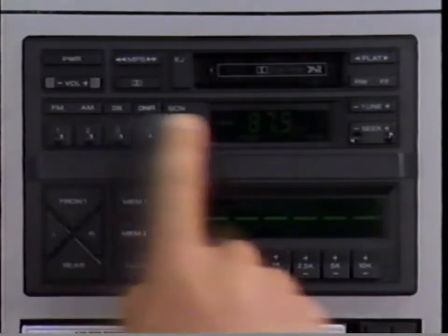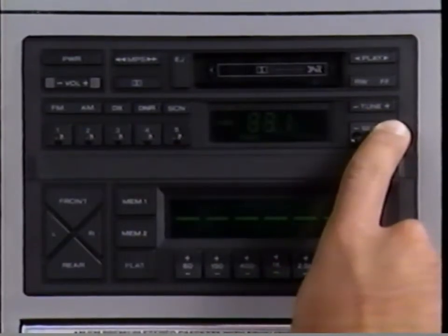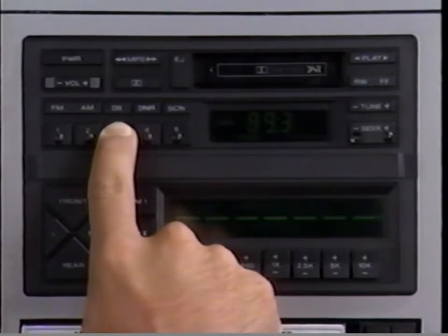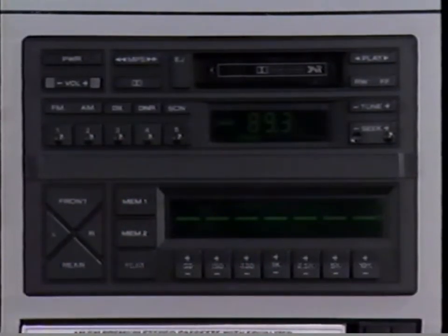I worked on a Dodge Monaco, and the radio in it had a self-diagnostic mode. When you pressed the M1, Seek down, Seek up, and M5 push buttons in sequence, the radio would send audio diagnostic tones to the speakers. Right. All Monaco radios will provide tones alternating between 200 and 6.9 kilohertz at 1-second intervals for a total of 60 seconds. Pressing any other push button, except eject and volume, will stop the test tones.